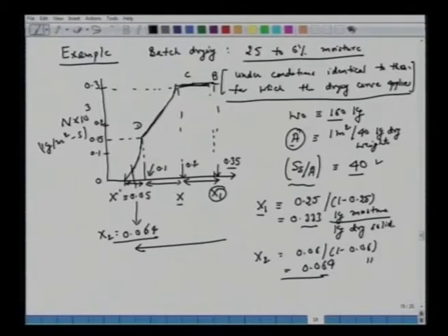Xc is one quantity we should note immediately, because we are going to use this. So this Xc is 0.2, and corresponding to this Xc we have Nc, which is 0.3 times 10 to the power minus 3 kg per meter square per second, as the graph was reported.